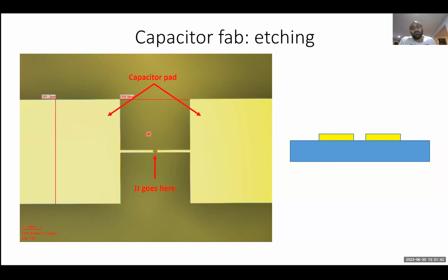For silicon, if you're doing a fluorine process, silicon is also vulnerable to fluorine-based processes. So if you're etching tantalum or niobium with SF6 or CF4, you will also attack the silicon as well. And so as a result, your silicon might also be partially etched and might end up being a little more rough as a consequence. And that can definitely affect the surface qualities of the substrate, the exposed substrate.